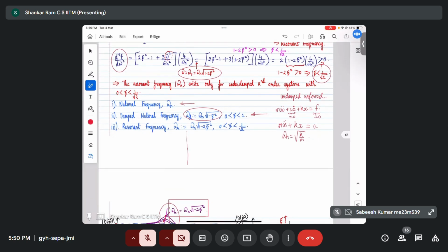So what happens is the following. Let's say we have the real and the imaginary axis, and we have this. There is a probability that there is a breakaway point. Please note, when we had this system for positive K, there is a breakaway point. For negative K, there was no breakaway point, because the branches went in different directions. I want to give a very qualified answer. Now the question is, what happens if we have a zero in between? Then it is very unlikely that we will have a breakaway point, but once again, you and I need to ascertain things.